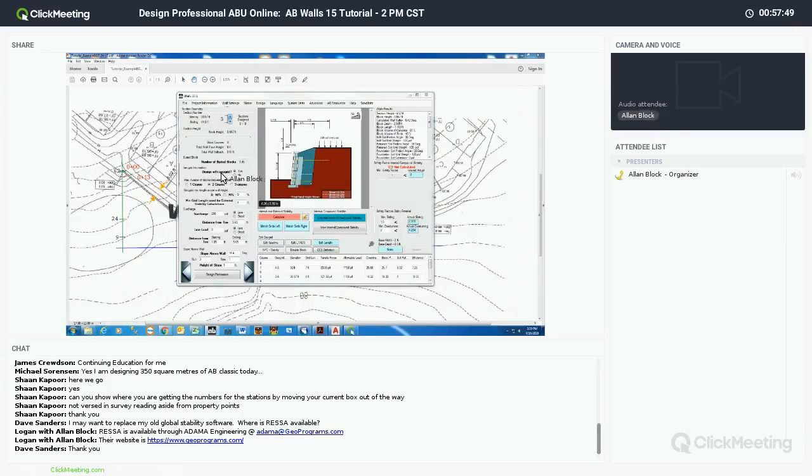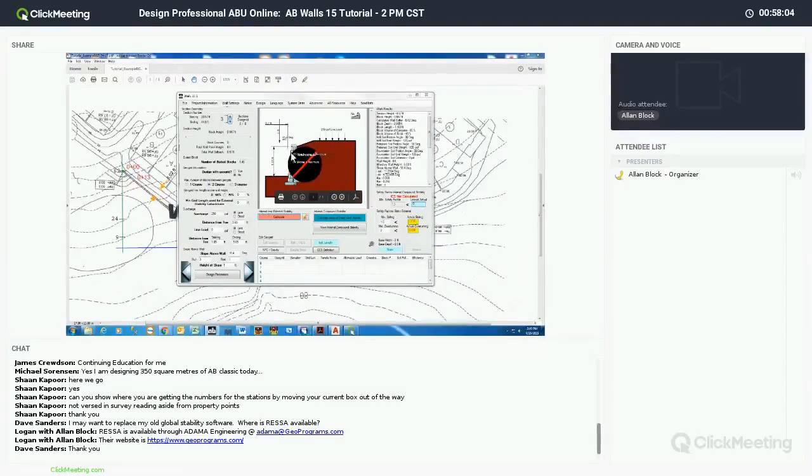So I'm going to go over to the left here and go Design with Geogrids to No. I'm going to hit Calculate because my Match Grids buttons have disappeared. The first thing that pops up is our sections do not meet safety factor. So if by some chance you gloss over that and hit OK, you also get this big Do Not Build section across your cross section. So it's going to tell you right away, don't build it and why. Your sliding and overturning factors are below minimum.